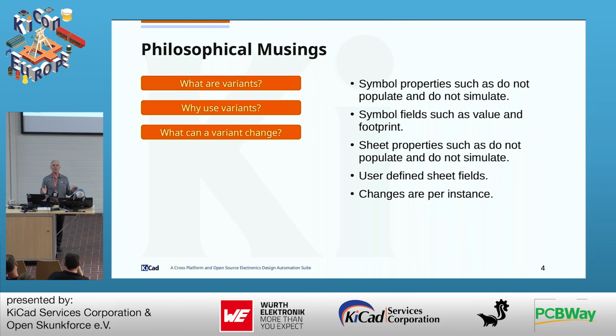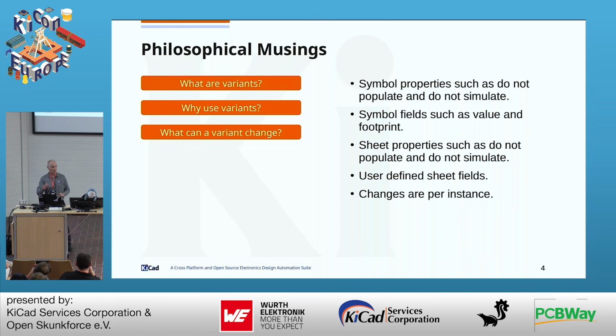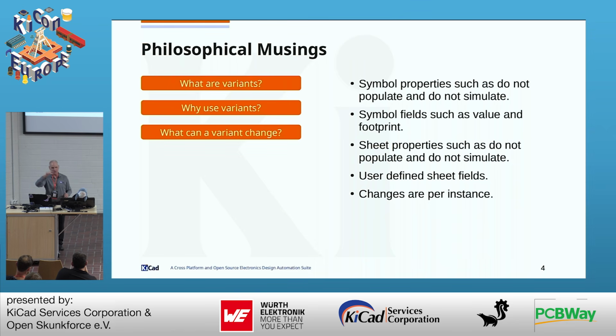Well, if KiCad only allowed you to have a one-to-one representation of a sheet and a schematic, we wouldn't need them. Everything could be contained in the schematic and it wouldn't matter because it would never vary. The problem is in KiCad we allow you to reuse that same schematic file over and over and over again. So now the instances change because those sheet paths change. Each one of those full paths that points to that file changes. And that's what an instance is.